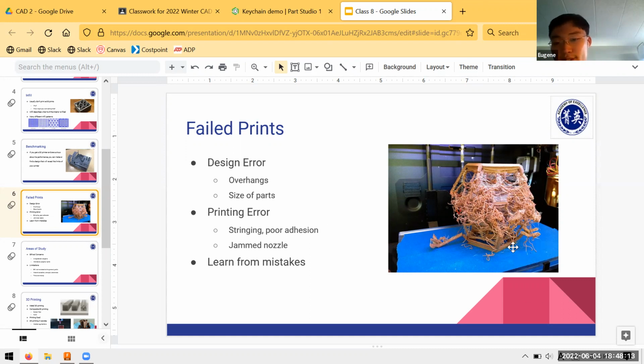You might get issues that lead to things like what you see on the right, where the extruded material isn't sticking that well to itself, or when you're rapidly traveling between different features that shouldn't be connected, there are still melted strings of material that follow the printer head around, which causes excess stringing all over your part workspace. Your nozzle can jam, which is pretty bad. But as with anything, the goal is to learn from your mistakes.